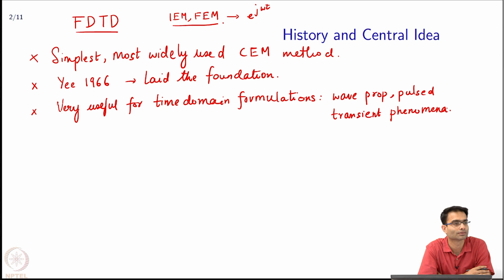Natural phenomena. Huh? Switching, yeah, okay. So that's a more down to earth example. Switching, right? There's a circuit, there's some switching happening. So that's your EMI, EMC as they call it, electromagnetic interference problems. There is some gate that is operating at some switching rate, and because of the switching, it is producing some electromagnetic waves. That was something naturally in the time domain.